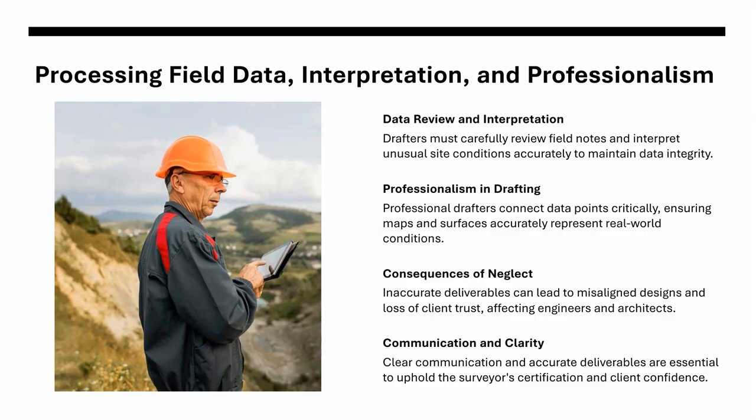Anyone can import points into Civil 3D, but not everyone can think critically about what those points mean. You must connect the dots, literally and figuratively. You must ensure that the line work represents reality, and you must check that surfaces make sense. You must question anomalies, ask the surveyor for clarification, and resolve inconsistencies. The consequences of neglect can be severe.